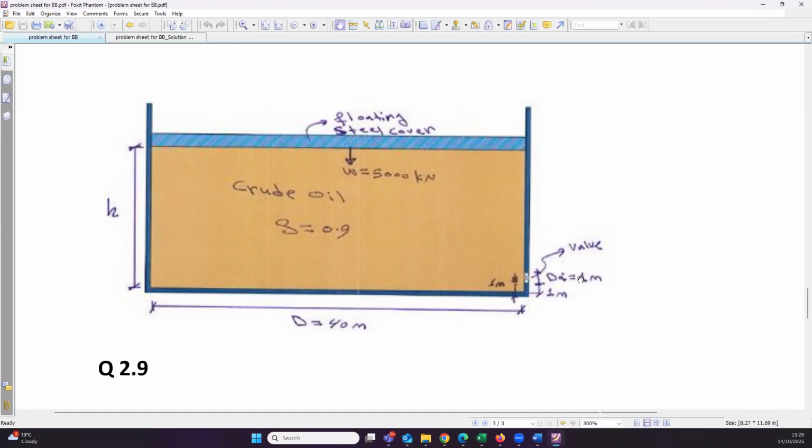Now, why are we adding 1 meter and then 0.5 meters, so 1.5 meters? Because, as I said, the pressure was at the center, and it means that when you calculated H based on this pressure equation, you got the height up to the center of the valve.